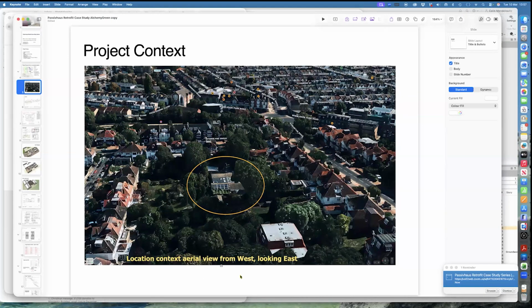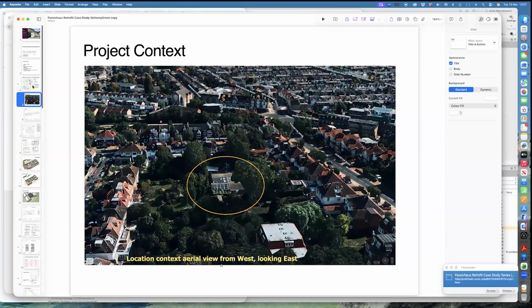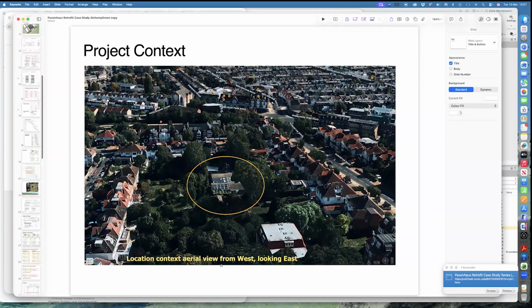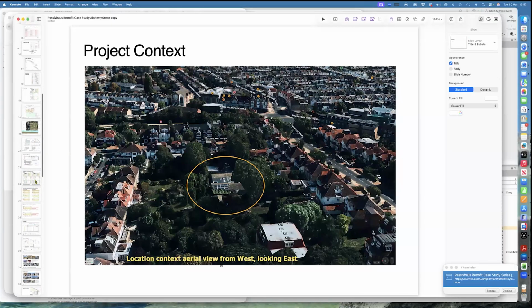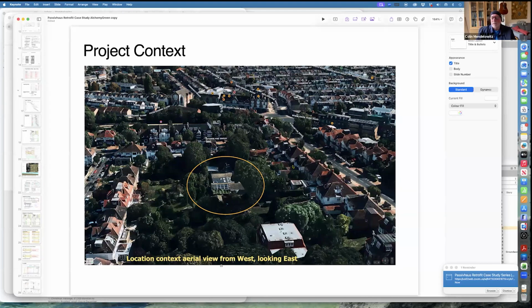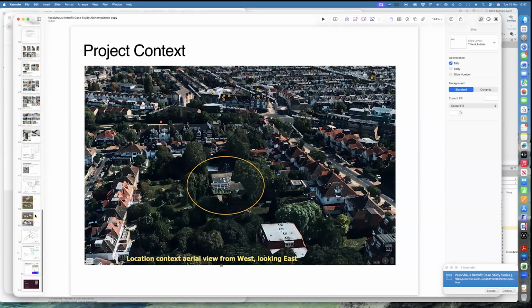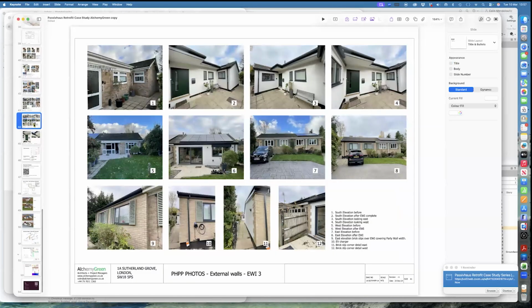On the west elevation, it wasn't in the original PHPP, but I wanted it because I knew the heat load was quite big on a summer evening. They do have external blinds on the big sliding door. They're not showing up in the pictures I took because that was a late delivery. Both the west windows had external shading, and they are great. They are on an automatic trigger, triggered by the sun, and deploy. You can see them on the big window, but not on the sliding door.